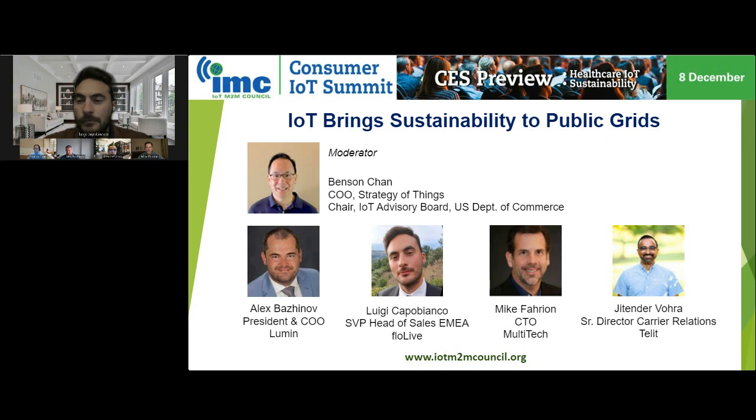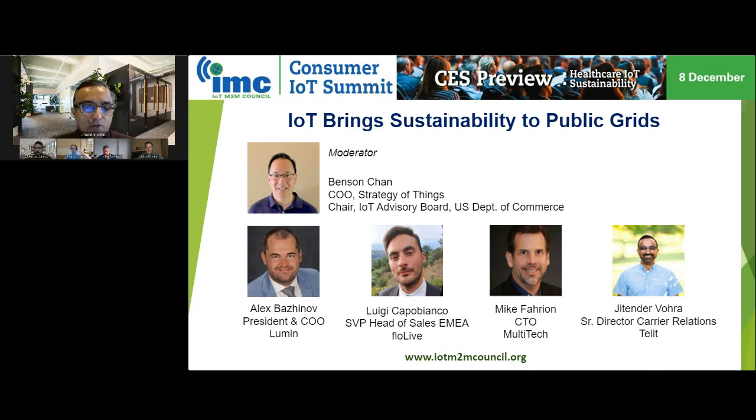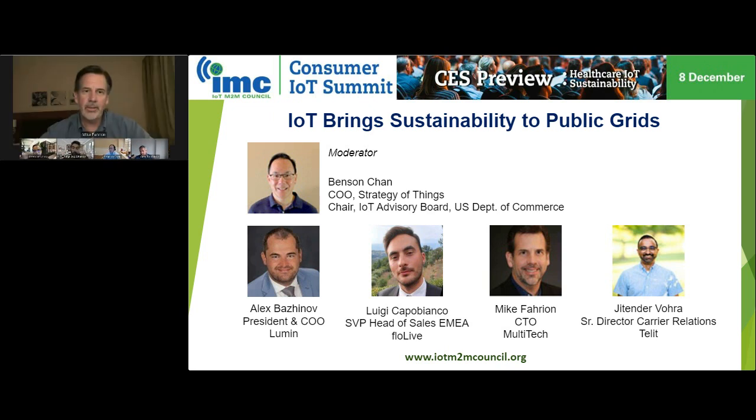Yes, I thought Mike touched upon this, but obviously there's no one technology that fits all. It could be LPWA, Cat1, Cat4, but the selection of the technology really depends on the use case and requirements of the application. But regardless of the technology, the intention is to connect things and make them remotely monitored, right? That's really what everyone's trying to achieve. Yeah, and I'd add there's a regional flair to that as well. Certainly at a technology level, like I said earlier, you have to start with how much bandwidth do I need, how much latency do I need, and how much power do I have available. You certainly can't battery power a 5G installation, for example, with a small long life battery.